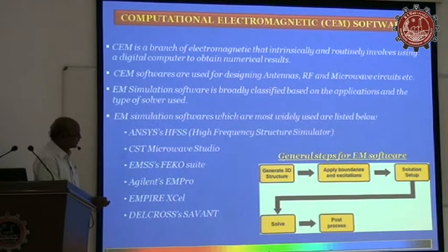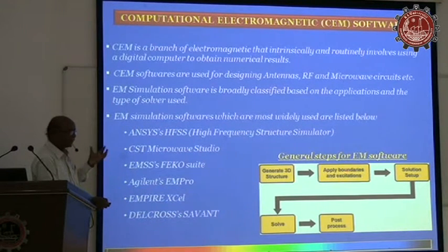So the software also has all the facilities to import the structure from, say, AutoCAD or SolidWorks, and then you have to apply the boundary conditions. This is also one of the important steps: how best you can define the boundary condition for that particular structure. That gives you the required performance.